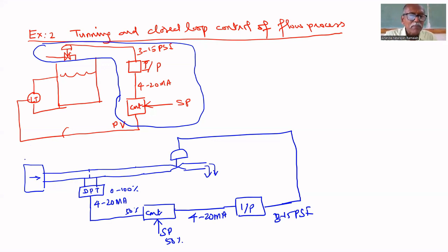It means the pump has to spend the same amount of power, irrespective of flow rate. Suppose flow rate is always 50%, the pump has to spend 100% flow rate power, but it uses only 50%. Power is wasted in the valve. This valve dissipates power. It absorbs some power by introducing resistance. That's why there is a large power loss.